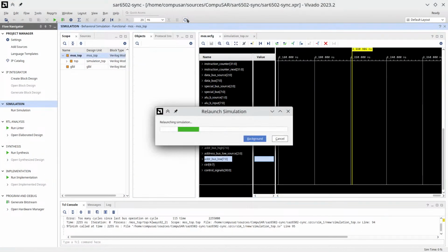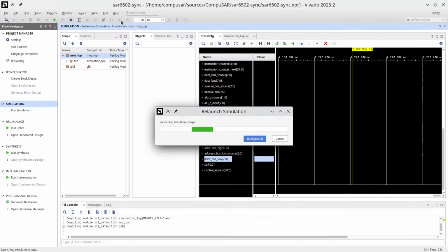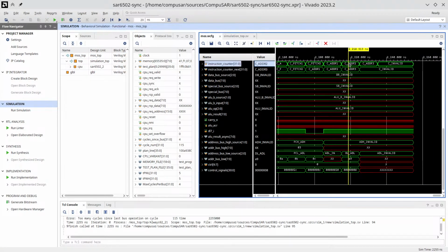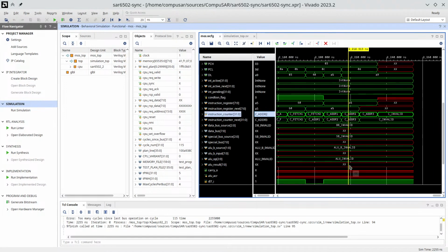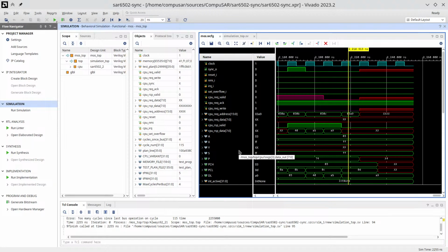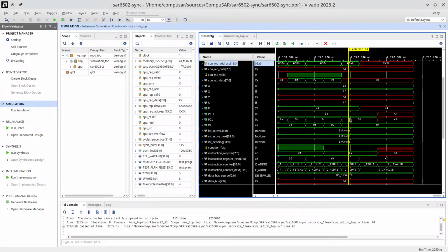And now, if we reload, ADDR2, we are supposed to see the CPU request address. The high value is 03 because that's what it was before, but the low value is A9 because that's what came from the DL, from the data latch. Okay, so low part handled.